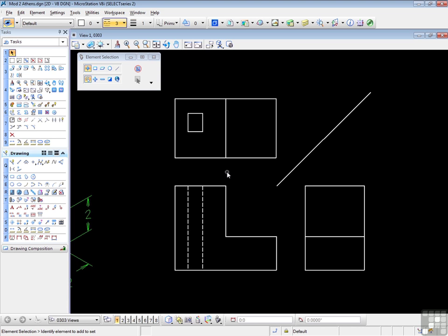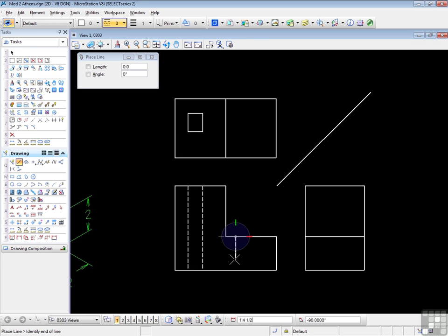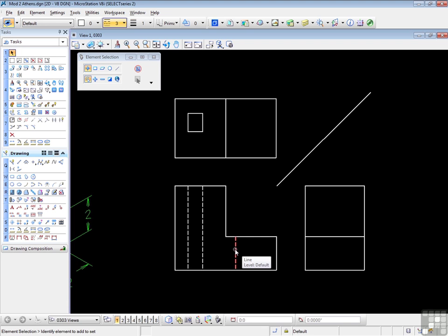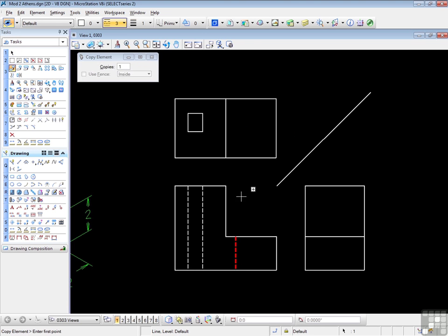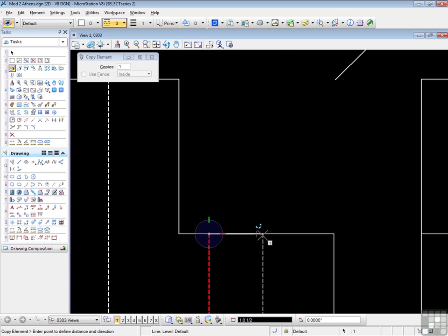Now, what happens under these conditions? Line tool is now on. I'm going to place another rectangular hole in here. So I want F11 and just the N key for nearest snap, enter an N, find that. Now this is purely arbitrary at the moment. I'm going to copy this and select the line, right click, copy there, and this is purely arbitrary.